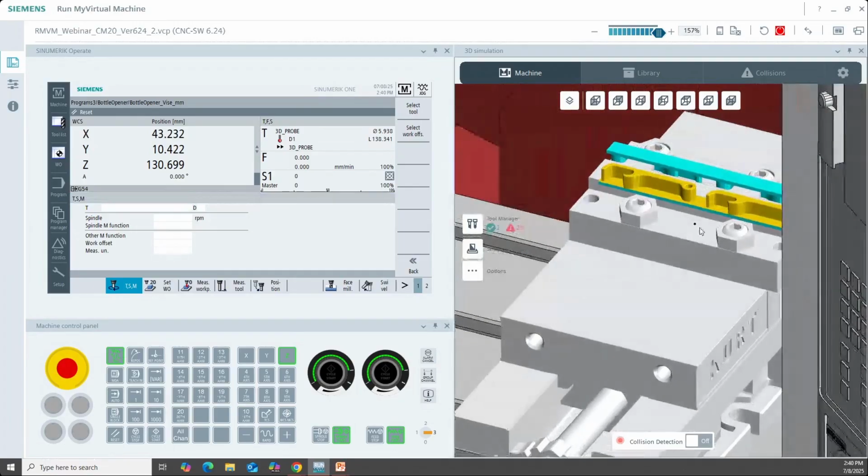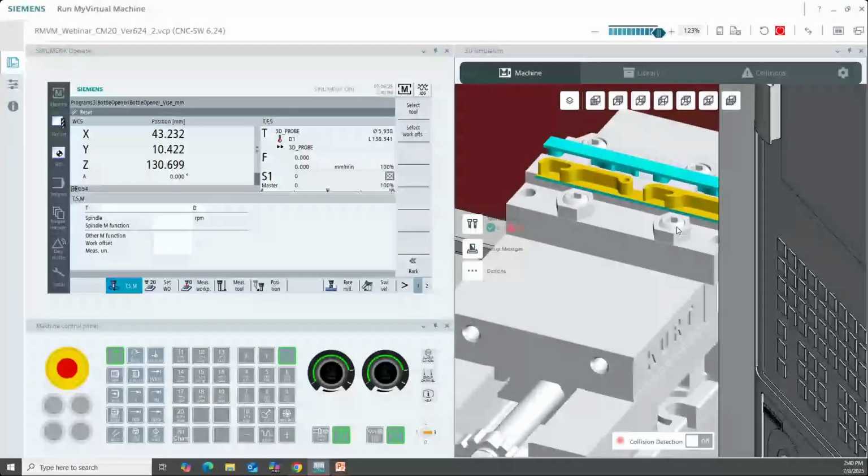We certainly need some form of a cutting edge to then apply that profile on the mating stock. But at that point, yes, we can cut the stock model. We can get the shape of the grinding wheel that's been dressed basically embedded into the stock model. Now, the stock model that you were looking at before is going to be the only thing that can be machined away. Anything else would represent a crash if I was to hit it.